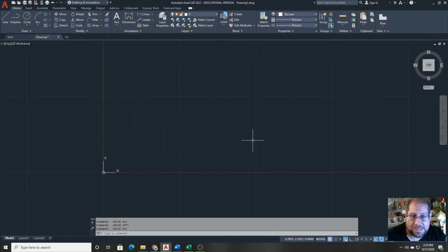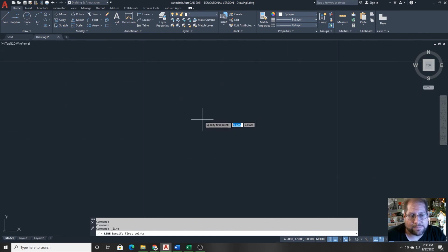Now here's the interesting part with the grid. You can use it to snap with, as you probably have figured out by now. If I turn that snap on, my cursor still behaves very smoothly when no objects are selected and no commands are selected. But once I select a command and I have that grid snap on, you can see that the cursor is only bouncing exactly on the locked spaces. And remember, I have my grid snap set to half. So it's bouncing at the halfway points in between each grid point.